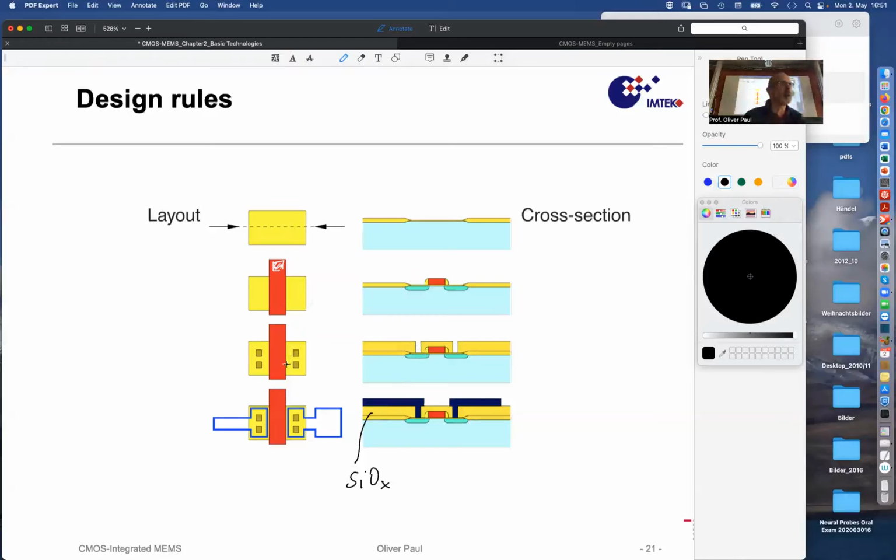So you might wonder why these little square pieces instead of one little long rectangle. Again, technology is something that requires to be reproducible. So if you can etch a square hole, a hole with square cross section, then you can probably also etch 2 or 3 or 4 of them. If you etch a slit, that's something different.